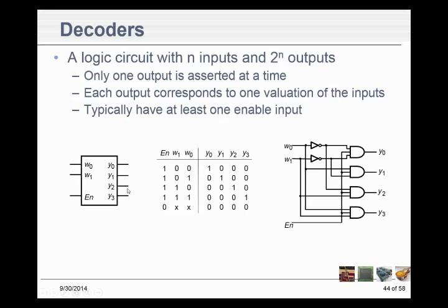When it's enabled, when we have 0, we're selecting this line, and this line goes high. The others we're not selecting, they stay 0. When we have a 1, this line goes high. The others stay 0. So we're only turning one of these on at a time by these two inputs. Have you ever done that before or ever needed to do that before? It's a little different. But for memory and selecting memory, that works out real well. And I can show you examples of why that's necessary. Okay. That's the decoder.